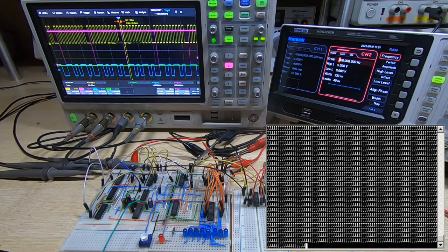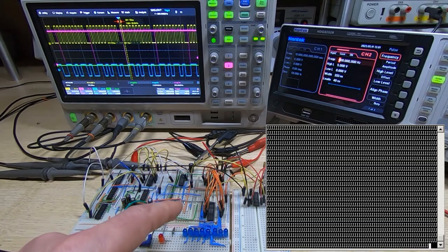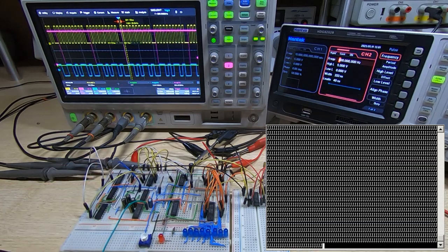So I'll press the key on the remote terminal keyboard and we'll send an uppercase A to our receiver, but we'll do that while it's still transmitting at full speed. We should see the red LED come on. That's the interrupt output line from this circuit, and as you can see, the interrupt has been thrown.